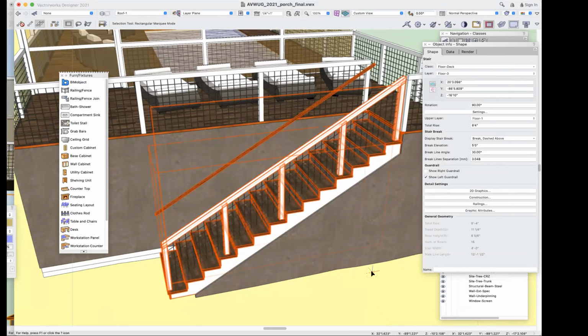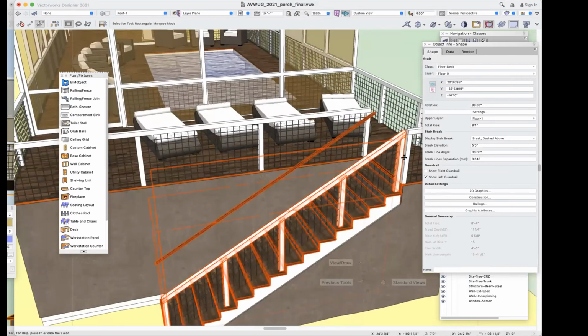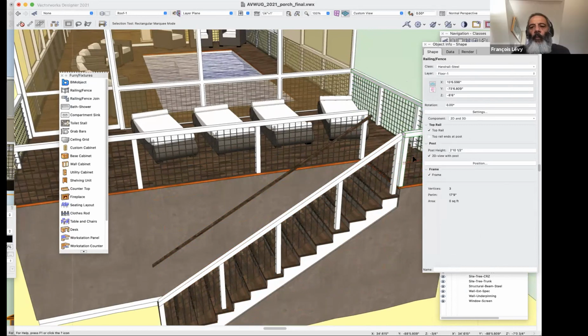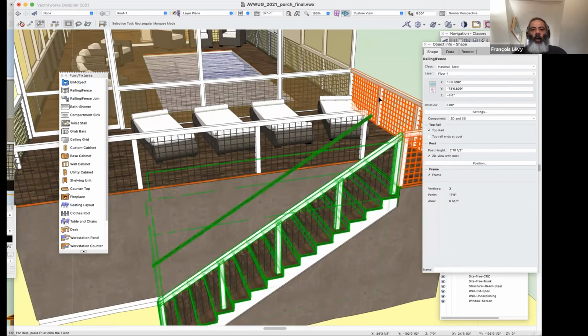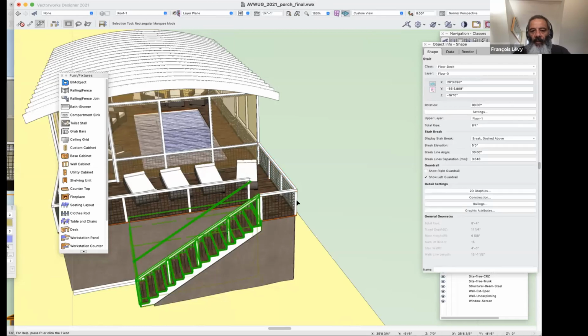And then if you wanted to merge the stair rail with your guardrail, is it possible to remove the top rail on your stair rail and just accept the guardrail as that rail? You have two rails right next to one another. Probably the other way around. I would eliminate the post on the guardrail and extend it to the stair rail, or I would use the 3D mode on the guardrail, just not have one on the stair, and then draw it along that three-dimensional path.